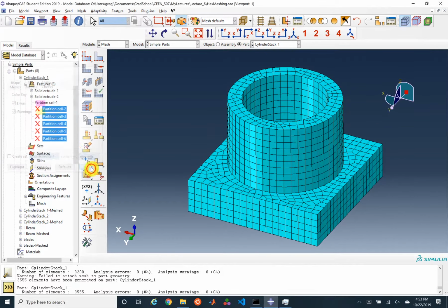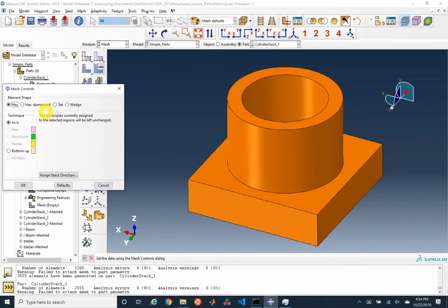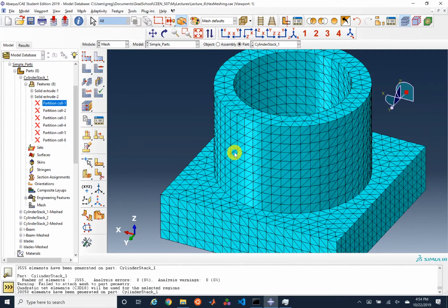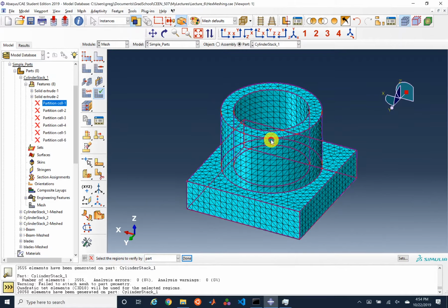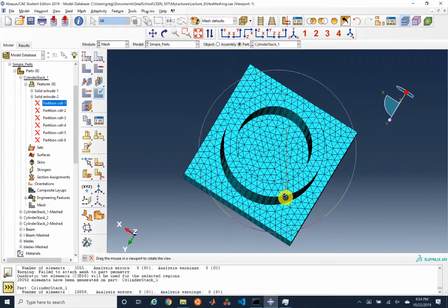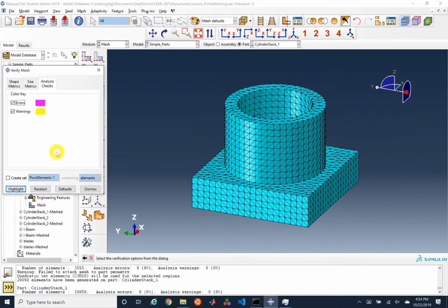If we go back all the way, again, these are quadratics. We plot the mesh quality, and we'll see that it also is of high quality. This is a very simple mesh, but I want you to practice, as we construct meshes on different geometries, going through and running these checks to see whether or not you have a good mesh, and also to see where the poor elements are.